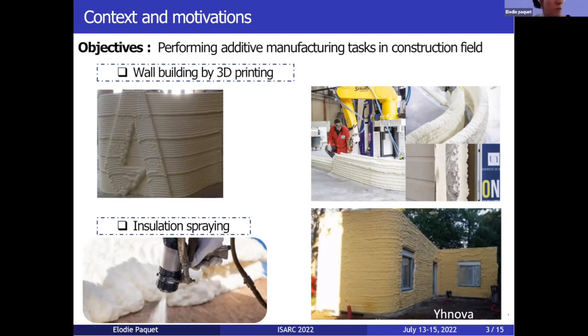We use a cable-driven parallel robot in this presentation because, compared with traditional robotic systems, cable-driven parallel robots have a large workspace that includes the printing area. In addition, the potential of reconfigurability of the CDPR is an asset to avoid collisions between the cables and the environment during the execution of a printing task.